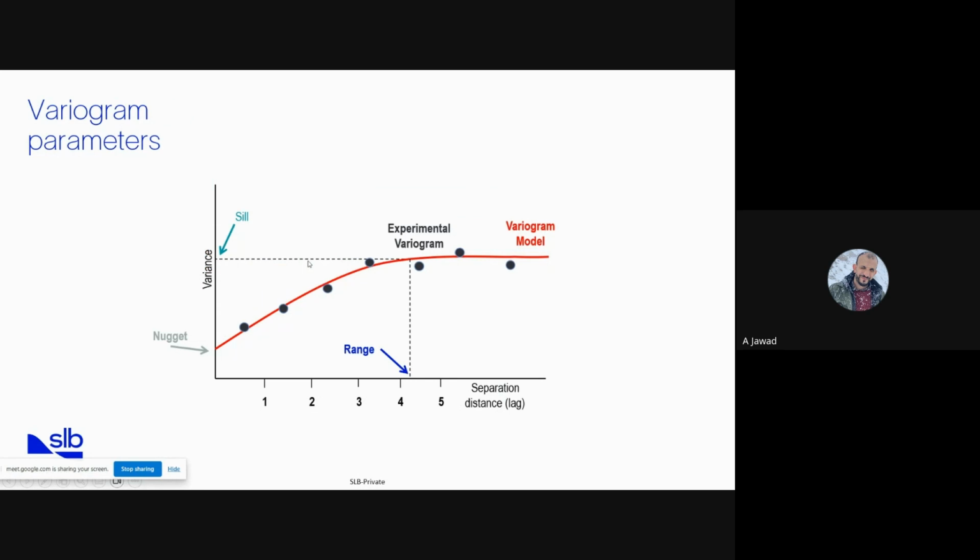After that is the variogram, which is the one I told you earlier that we are spending most of our time working on. In this variogram, we are modeling the variance of my data. We are testing and modeling the variance in the vertical direction, and we are doing it in the horizontal direction. And not only in the horizontal, we are doing it also in major and minor. I will discuss this later in the next slide. So this is the component of the variogram.